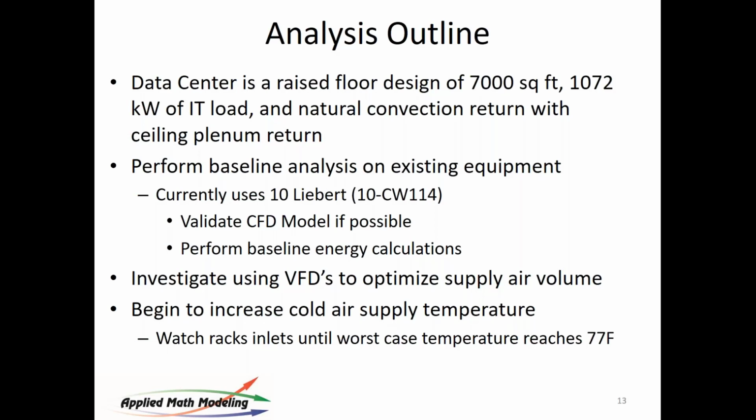In other words, you want it to reflect the real world situation as much as you can without getting so carried away that the model becomes too complex, the time to compute it gets too long, and it gets too big to handle. You want to perform some baseline energy calculations. And then in this study, we're going to take a look at using VFD to optimize airflow volumes. In CoolSim 4.6, the new release, we have an ability to do that in the modeler, and it will predict for you the energy delta associated with the change. That's what we're going to show you today. We're going to look at the rack inlets, and we're going to optimize the case until we get to about 77F. And then we're going to stop and see how it looks.